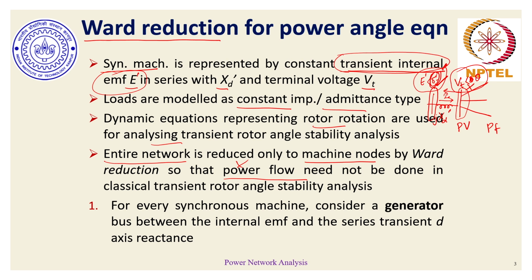One can always counter question and argue why is this assumption necessary. I would recommend, for the sake of understanding the concept, yes, this assumption might not sound logical, but to understand or have a premise, yes, it is useful for understanding that. In order to do more complicated analysis, specifically for multi-machine transient angle stability analysis, Ward reduction may completely be avoided and exclusive power flow may be done, and then corresponding initial operating condition may be obtained, but with a warning that transient rotor angle stability analysis is a limited time period of study.